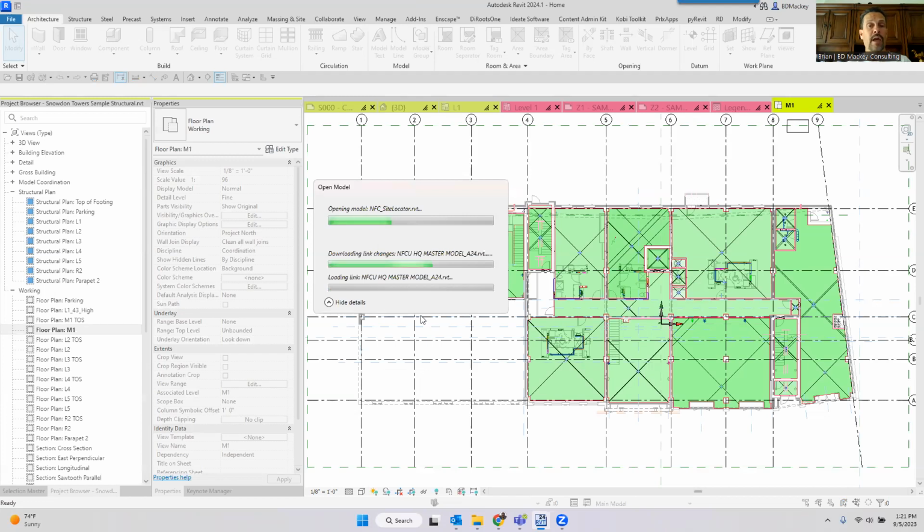I've acquired coordinates from that, so my survey point may or may not move, but I will get my northing and eastings. I then link my Revit file into my site locator, and I rotate it, I elevate it, I move it where it needs to be moved to. Once I do that, if I'm not on BIM 360 or the Autodesk Construction Cloud, I can simply publish the coordinates back to my own architectural file.